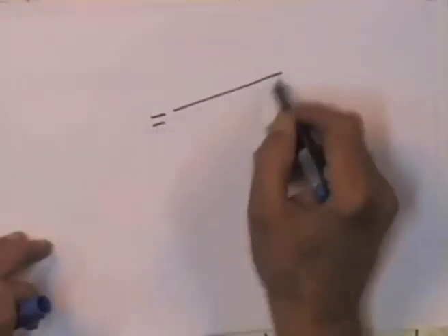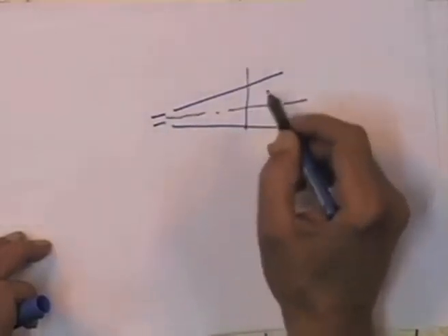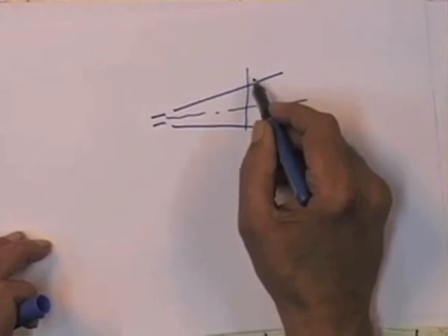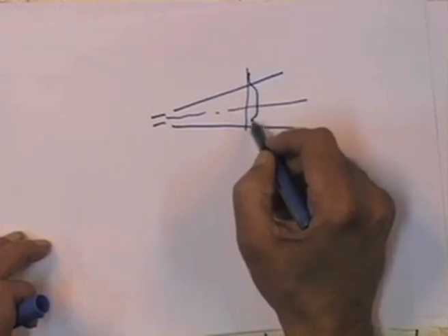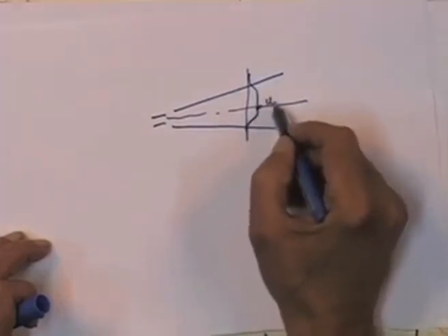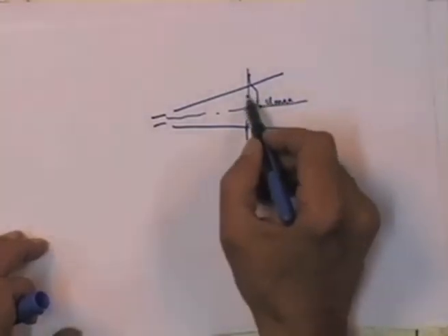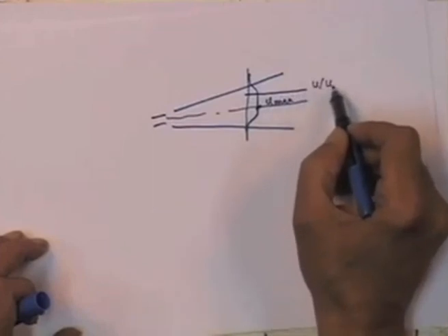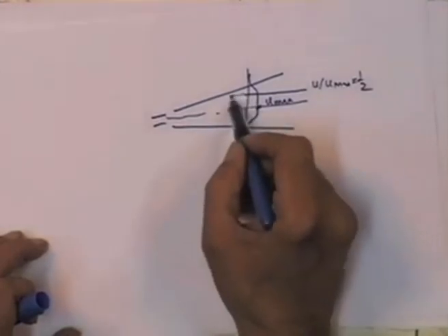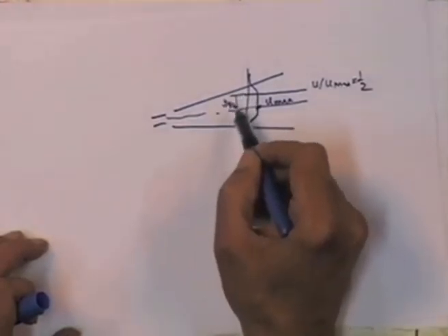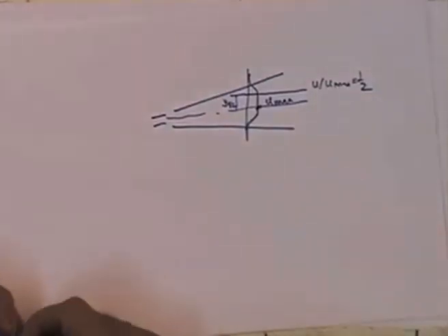Let us say the jet is emerging, then this would be the velocity profile, and this would be u max, and wherever u divided by u max is equal to half, that is the distance y half. This is called the half jet width in a free shear layer.